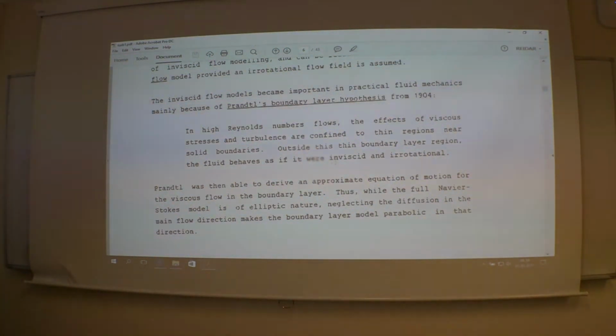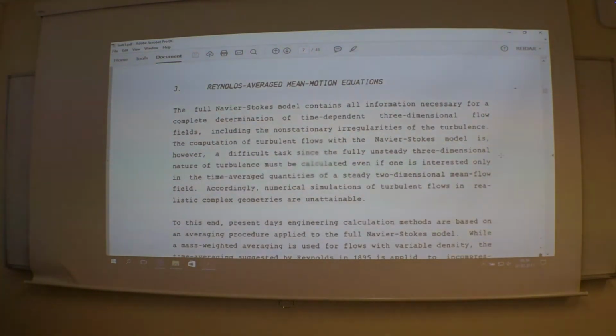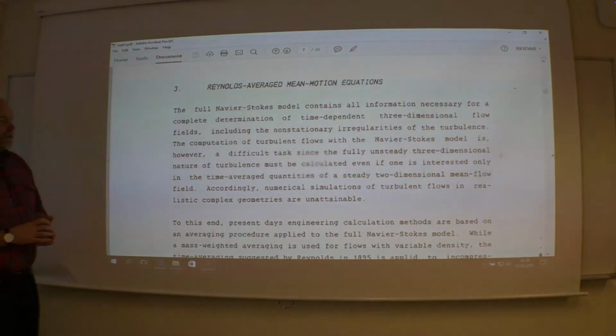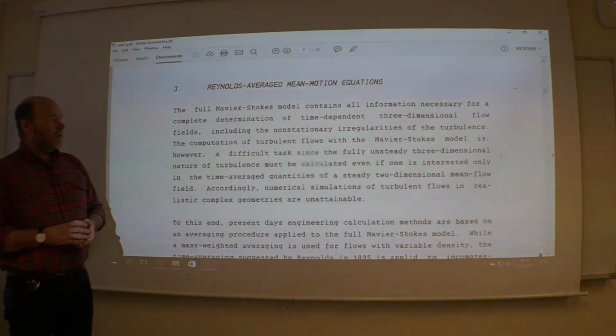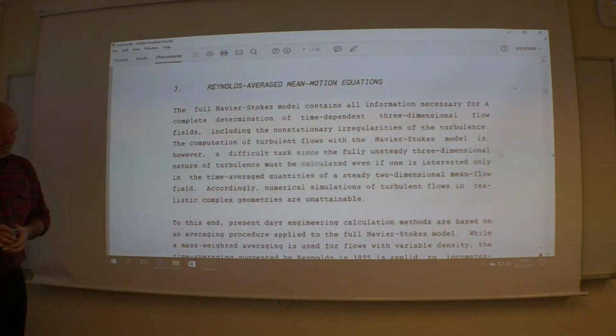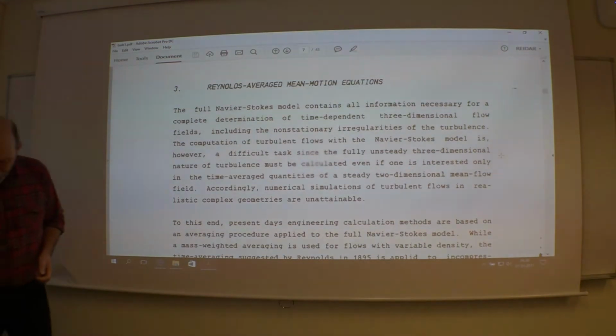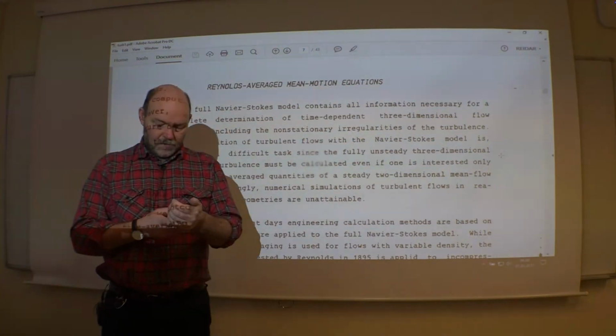It should be okay. You can even use Euler codes if necessary, and then do something within the boundary layers. But that's sort of not so very accurate. So here we are jumping directly into the family of RANS methods. So how to achieve a RANS equation.